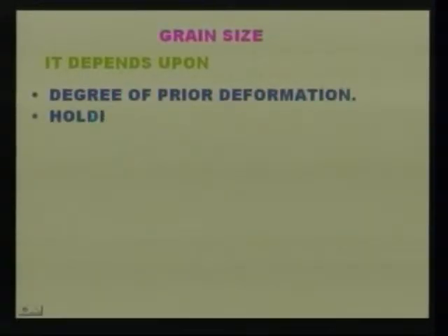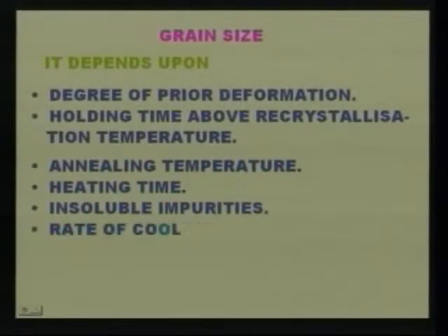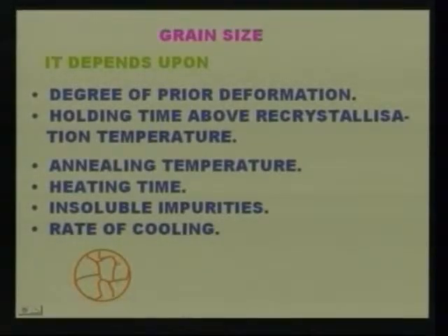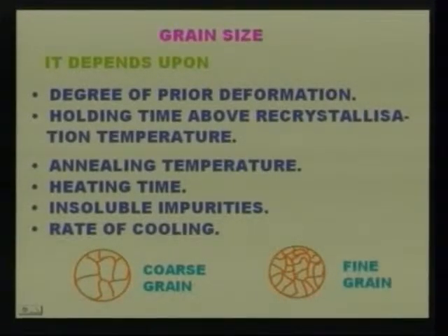Now, let us see the grain size after recrystallization. It depends upon the degree of prior deformation and the holding time above the recrystallization temperature. It depends on annealing temperature, heating time, insoluble impurities, and also the rate of cooling.